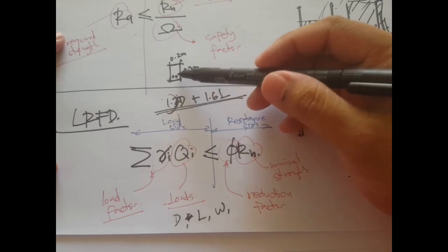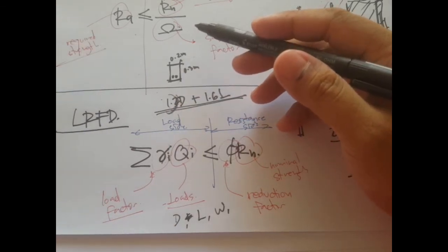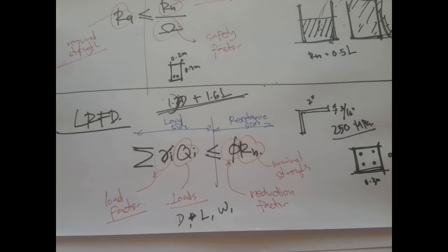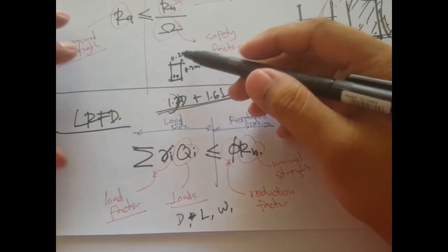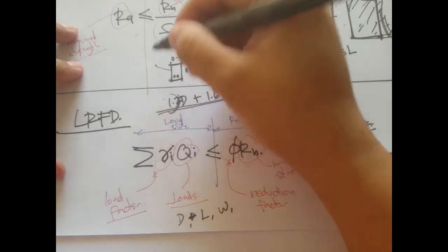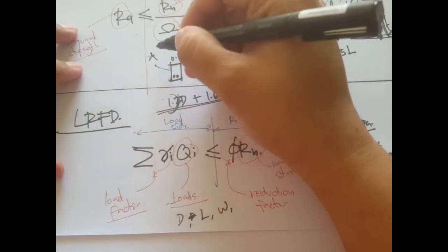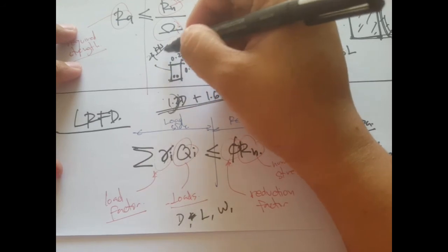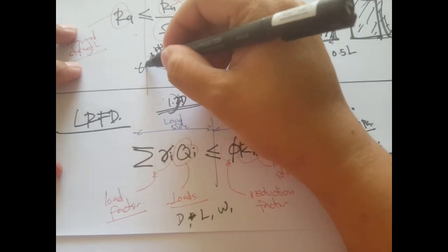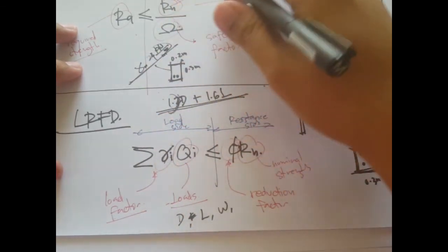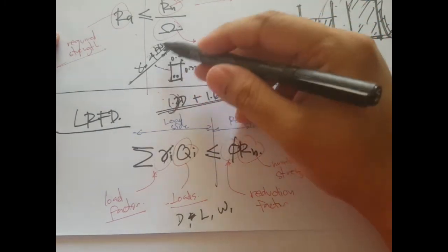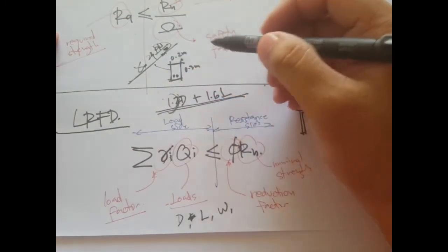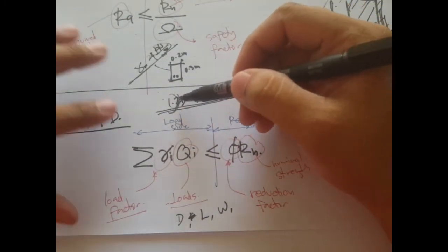Plus the data on the unit weight. If I remember correctly, for reinforced concrete, that's going to be 24 kilonewton per meter cubed. So that's the unit weight of concrete, but in reality it could be different or slightly off. So that's why you have this 1.2.